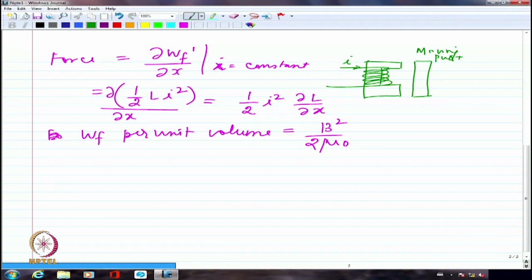If you look at the evaluation of L, it will be a continuous function because you are not seeing abrupt movement. It's a slow motion, probably starting off from x1 and then moving until x2. So you are looking at the air gap gradually decreasing. So you will have a continuous variation in the inductance because you are going to see a continuous variation in the reluctance.